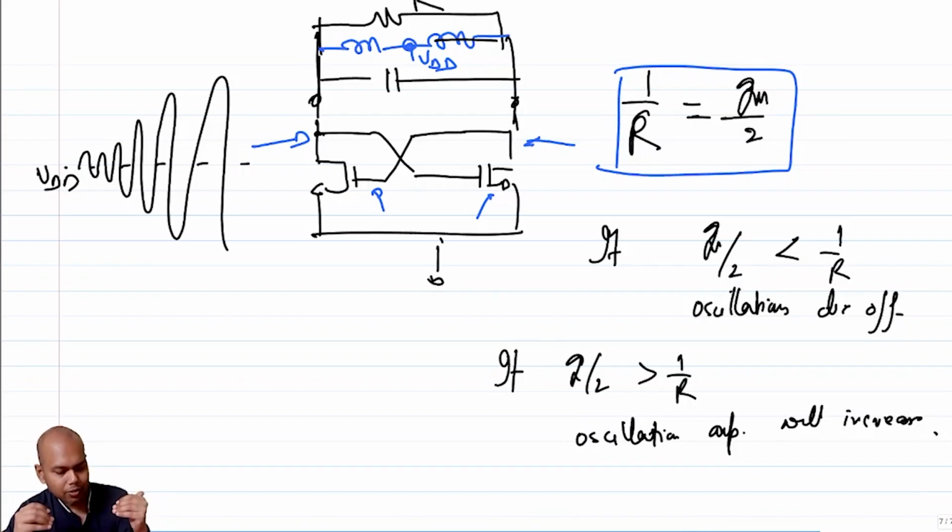So the good thing about an oscillator is you do not physically have to match a design where the negative resistance exactly matches the positive resistance. If that were the case, it would have been trouble, because in a semiconductor you cannot ever match everything effectively, right? There will always be some deviation.